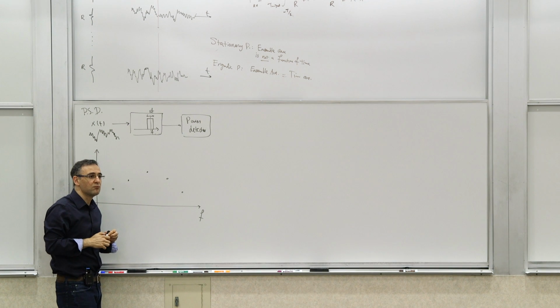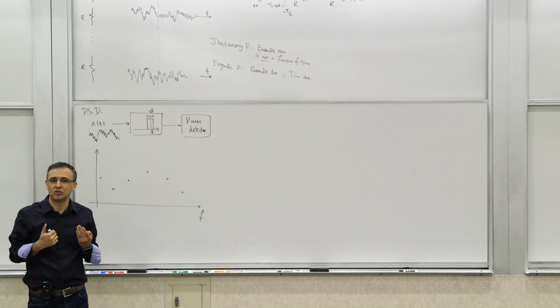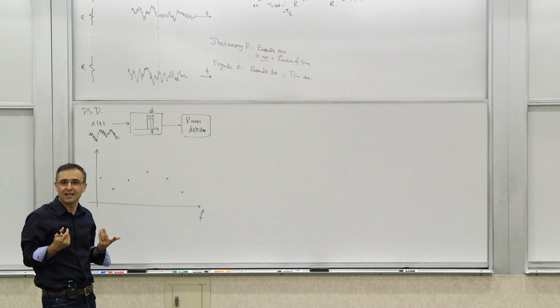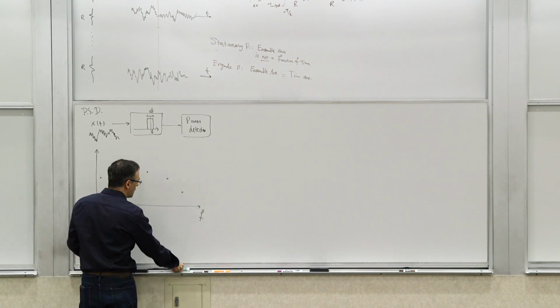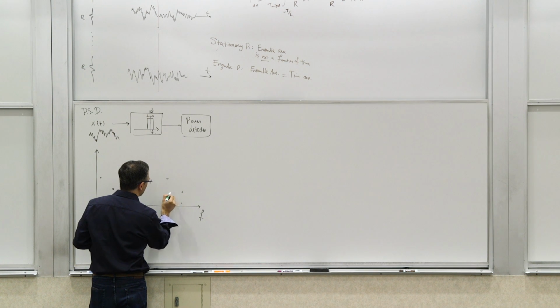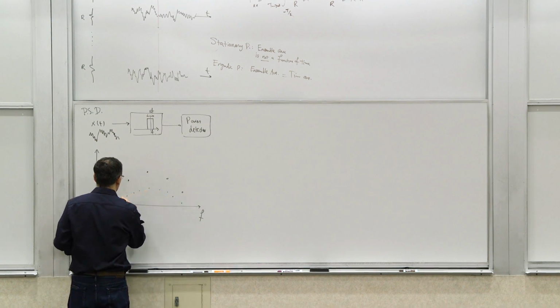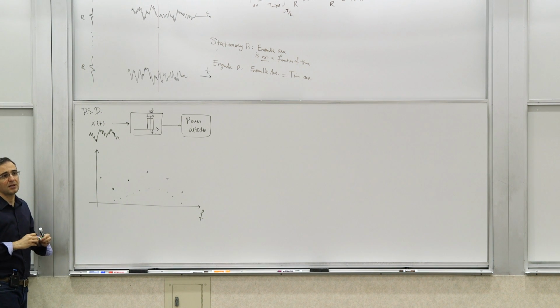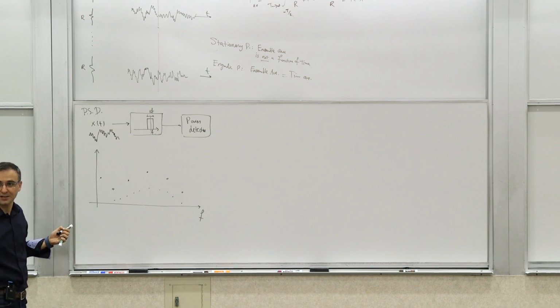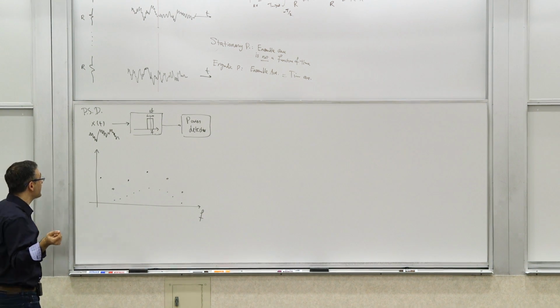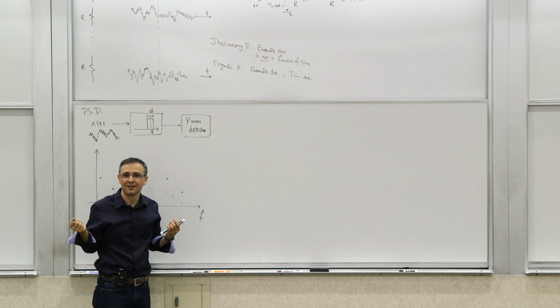If you shrink the bandwidth, would you get more or less power in general? You get less, because there's less of the energy going through. So if you just shrink it and plot what you measure, you will get points here, here, here, and as you shrink delta f, this is going to become smaller and smaller. That's not a good way of doing it, because you ideally want a continuous curve that describes the density of the power, how much energy is exactly at which frequency, which basically means that delta f needs to go to 0 in the limit.